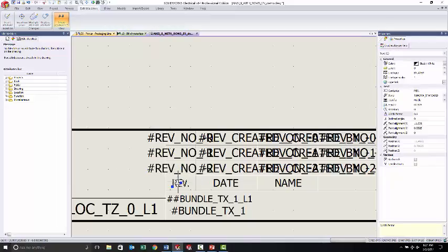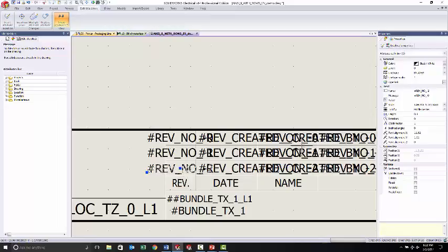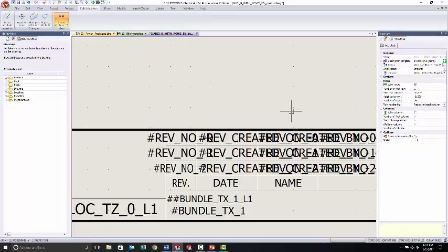By cheating, I can highlight the text, which gives me all of these, and now when I go to the attribute, I now have all the same type of aspects. So I can cheat by getting into it now, and I can actually change the width factor of that specific attribute the same way. Couldn't do that before. You could, but it was a lot more difficult. So just some things, and it's more for cleanup.